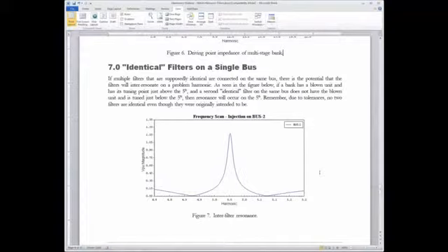They put smaller ones. So they created a condition where they had one filter properly tuned around 4.9 or something like that, and the other filter, because it had less kVAR in it, the tuning point had gone up. And these were connected onto the same bus.